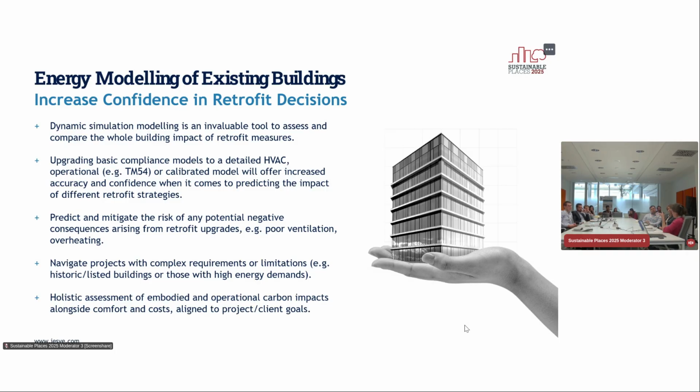So from those meter readings, once we know that they're clean and trustworthy, talking to the occupants, talking to the building owners, then we can actually understand how the building operates in the real world. And we then use that to make accurate energy models to predict the performance better than a compliance model. So we make calibrated energy models, so that helps the designers understand where the actual design is, the actual energy demand is, and where the opportunities for savings are.